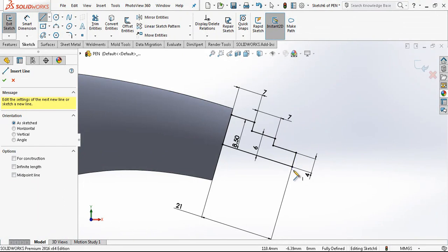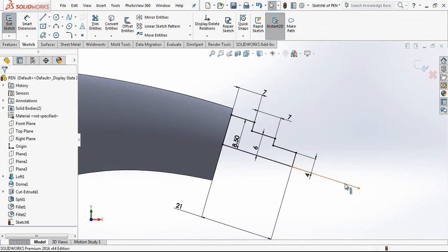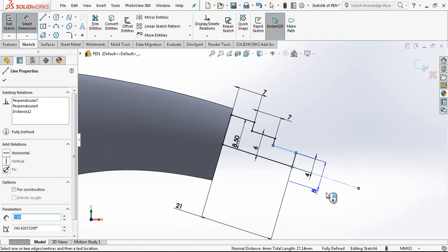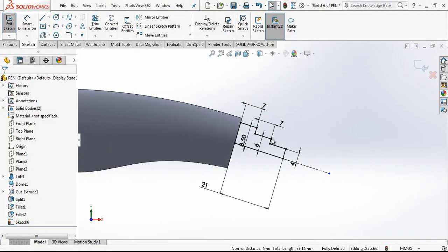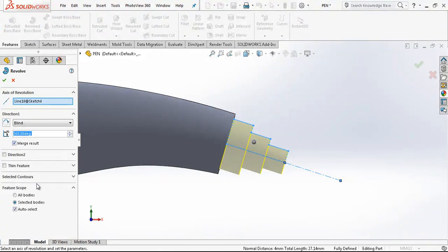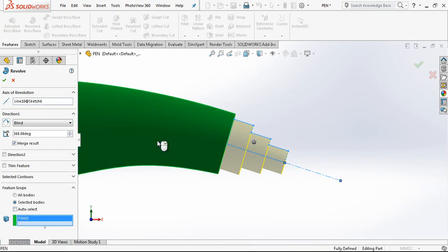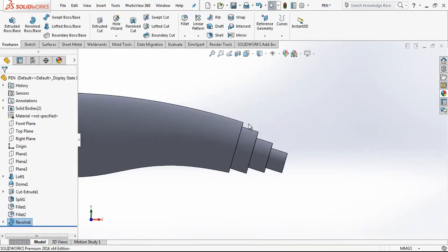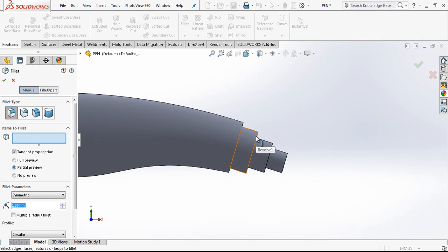There is an easy way, in fact, to do it without dividing the dimensions with a construction line. When you go to the other side of the sketch, you can see the full dimension instead of radius. This is also easy. If you wanna use, you can also use that. We're gonna make merge result, and now radiuses.